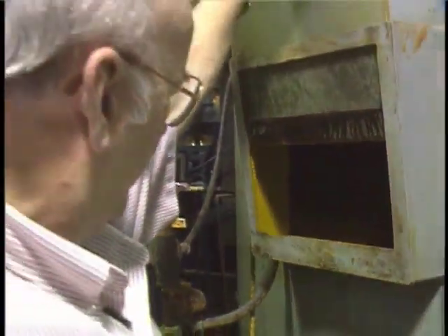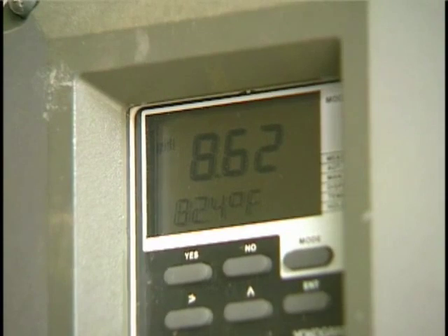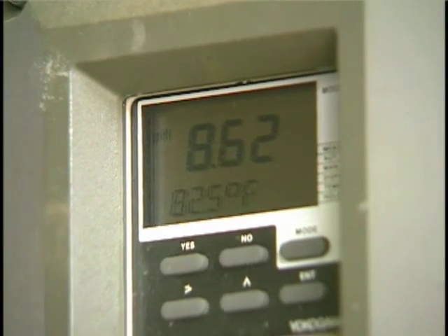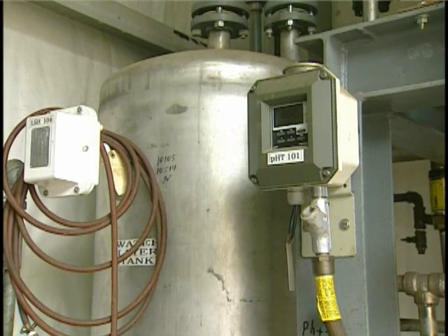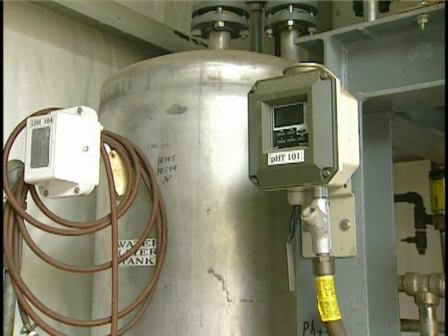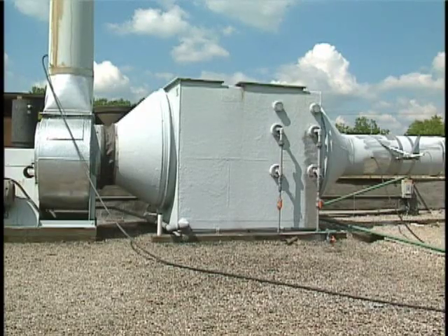The pH of the inlet and outlet liquid should be evaluated. An inlet pH above 10 indicates a potential for scale accumulation that can plug nozzles, packed beds, and trays, reducing liquid flow rates and impairing gas-liquid contact. An outlet pH below 6 can cause severe corrosion of metal components.